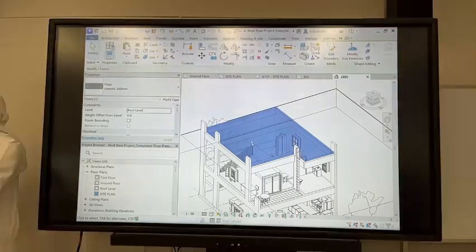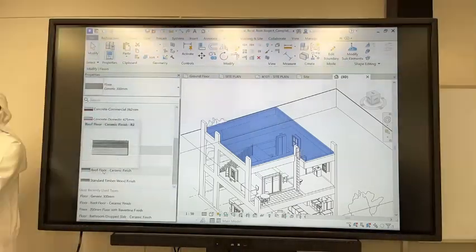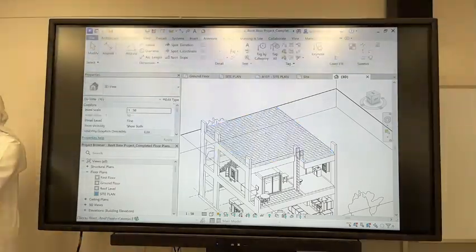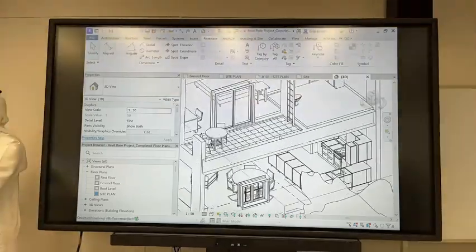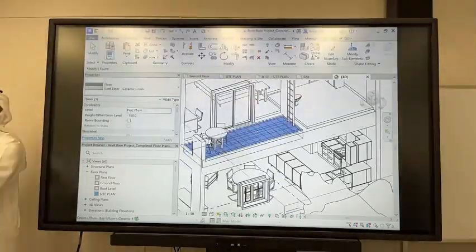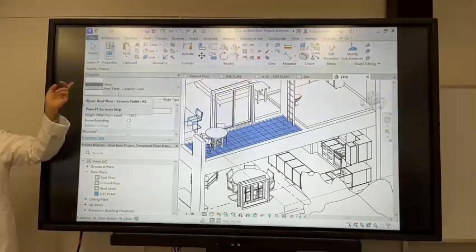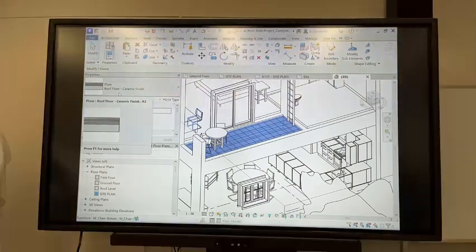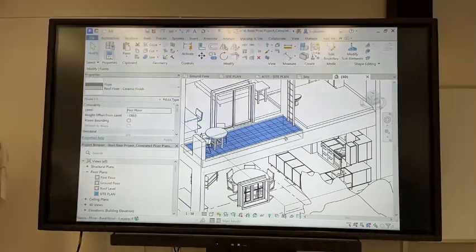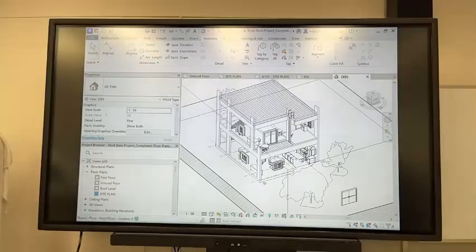Select it. Drop down in 300, label to roof floor ceramic finish, and check that the hatching changed. Do the same thing for the balcony. Roof floor ceramic finish. Now by name we're going to customize it. I'll show you how. This name, it's fine to keep it as that. So you can change it in another view like 3D and then go back.